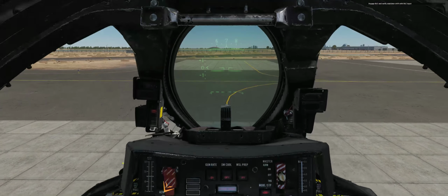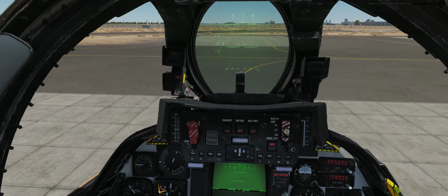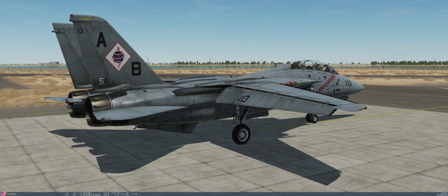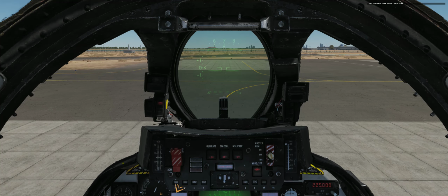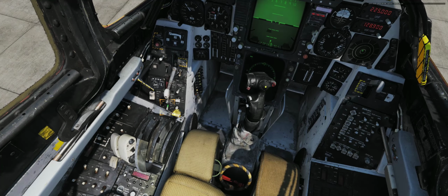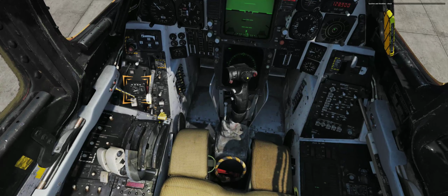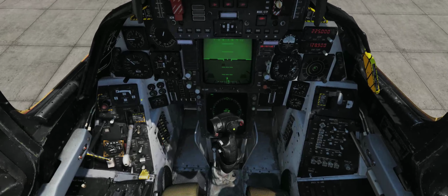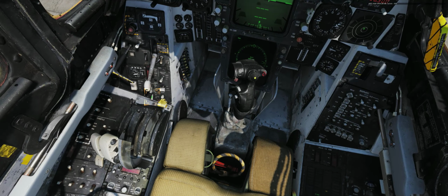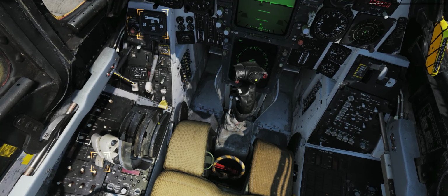Toggle DLC and verify stabilator shift with DLC input. Set anti-skid spoiler brake switch to spoiler only. Test spoilers and throttles. Set anti-skid spoiler brake switch to off. Retract flaps and slats.